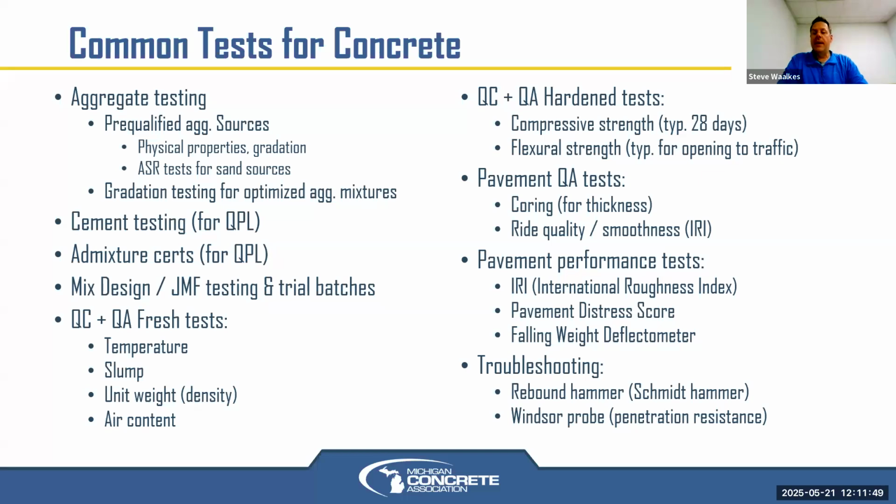But at any rate, another thing that they periodically sometimes do on concrete pavements is a falling weight deflectometer to measure the response of the concrete slab, the deflection of it underneath a given load that's applied to the pavement. So they're typically trailer mounted devices that are brought around, and then they have to stop and then do that loading. And there's sensitive measurement being done of the deflection of the slab underneath that load. And from that, they can back calculate a lot of different things, not only the concrete things, but the support layers below it. And they can back calculate some support conditions.